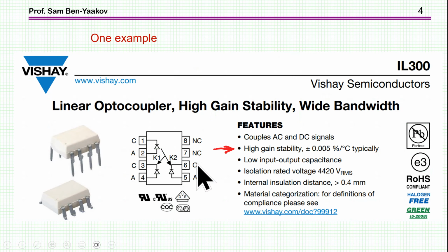On the other hand, we have here a device which has a LED, a light emitting diode, like a regular optocoupler, but then it has two photodiodes, in this case shown as photodiodes, though actually they could be phototransistors. The same fraction of light is impinging on these two light detectors. So this is an arrangement around which you can build a linear amplifier.